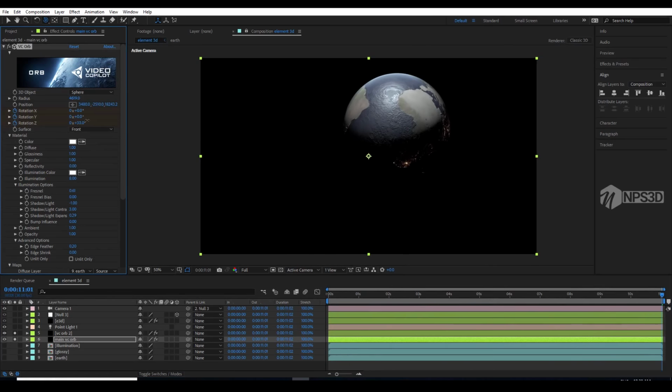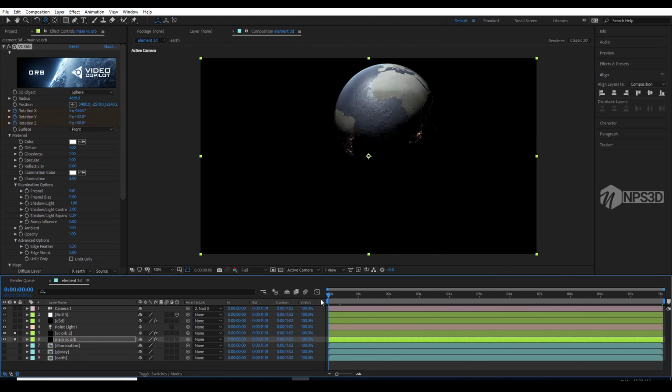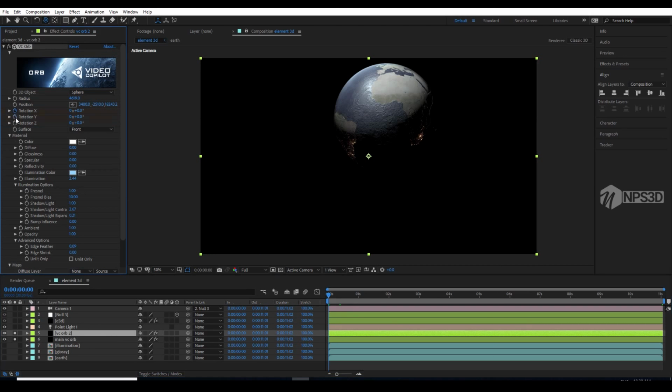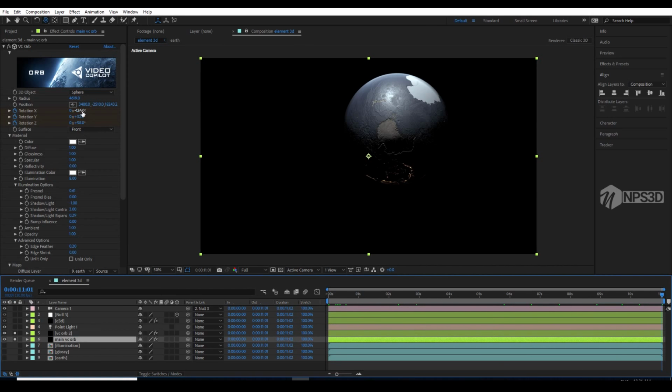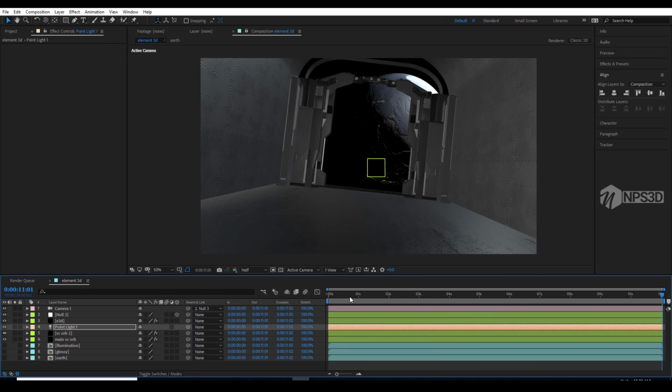And just rotate it. And same animation keyframes for our first one also. Select the first one, add X, Y and Z, go to the very end of the video and just copy this position -1 to 126, 32, and I think your scene is good enough. You can change the animation of our planet model also, but we are good to go.